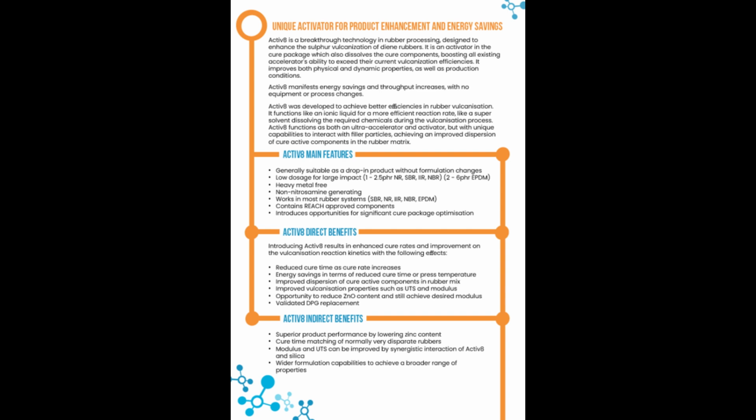Activ8 indirect benefits. Superior product performance by lowering zinc content, cure time matching of normally very disparate rubbers. Modulus and UTS can be improved by synergistic interaction of Activ8 and silica, and wider formulation capabilities to achieve a broader range of properties.